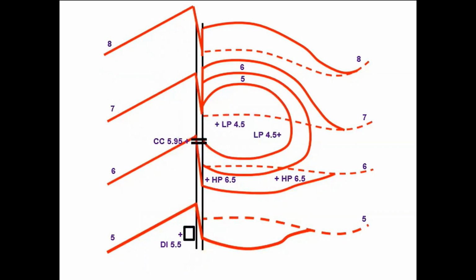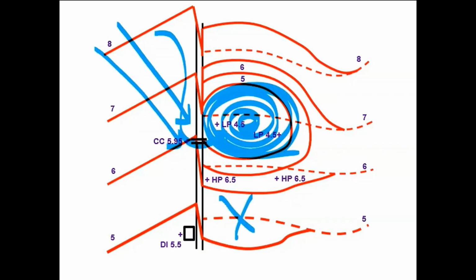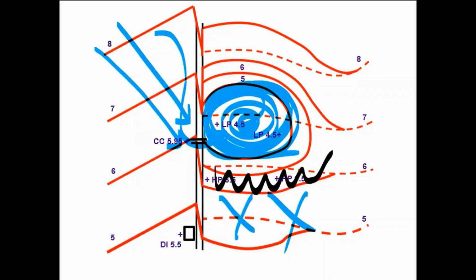So in this slide, you see we have taken out the raised drop inlet, and that is a perfectly fine way to do this. What happens then is water flows down, it goes into the curb cut, the retention area fills up, it does not overflow because we have a berm that keeps it from overflowing. What it does is it backs up in the system, and then as it backs up, the water will block the curb cut. What happens, of course, then is the water cannot go into the system anymore. So the cleaner water simply goes down to the drop inlet.